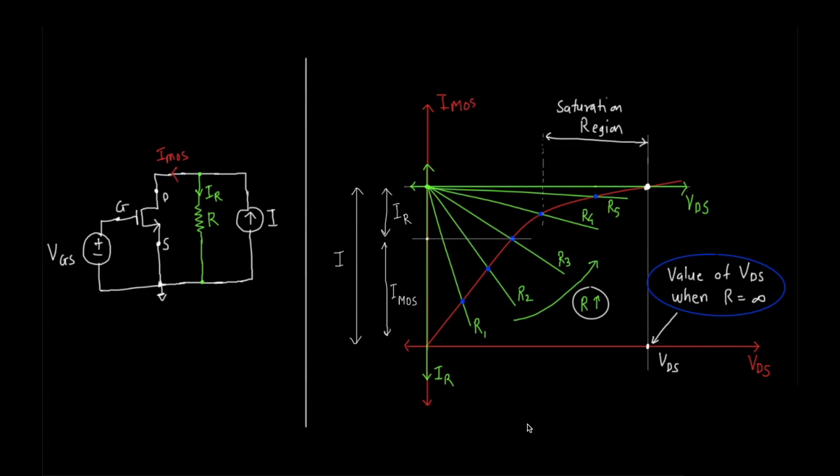Let's take the circuit with no R connected. In that circuit, we were having an external current source of value ID which used to set the initial operating point. This also used to determine the value of VDS. Well, we can try the other way around now. Let's set the current through the MOS by setting a fixed VDS.